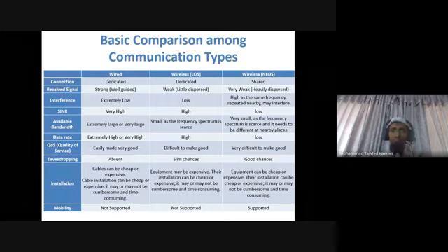In the non-LOS case, the power is dispersed widely, and you do that deliberately at the transmitting antenna, because you will be sharing this power with many different people. Consider the cellular base station. All the people in the cell will receive the power, so the base station transmits over a wide range, and people in different directions can listen.